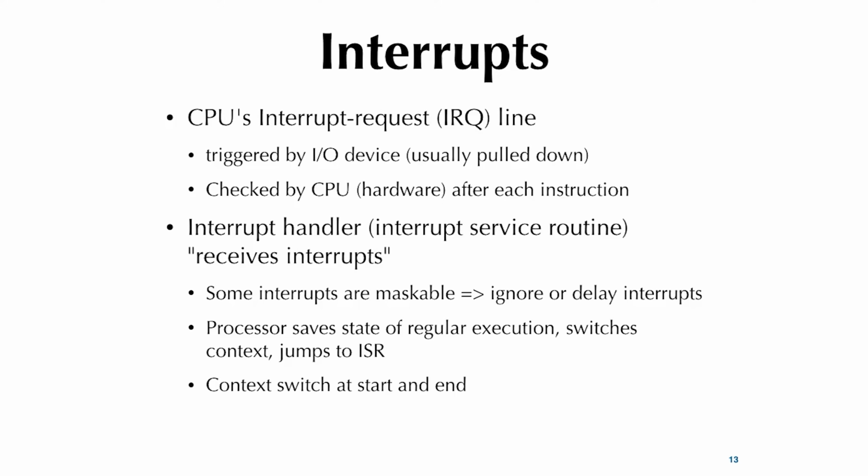So why would it do that? Well, it has to do with potentially sharing that IRQ line, because oftentimes the most precious resource on a CPU is its I/O pins. You can make so many other things very small, but you have only so much room on the outside, and these outside pins take up a lot of room compared to the die on the inside. And so a lot of times you can't afford to have one dedicated IRQ line per device. They may have to share, and I'll talk about that in a little bit.